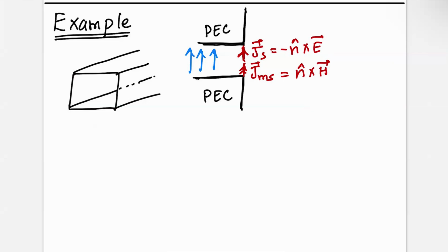So what does that do? That forces the fields on this side to go to 0. E equal to 0, H equal to 0. Right? So you have some currents and the fields on the other side went to 0, right? To satisfy that boundary condition, which is what we just looked at when we did the field equivalence principle. Right? Okay. So here we have used the field equivalence principle. All right, then what do I do?